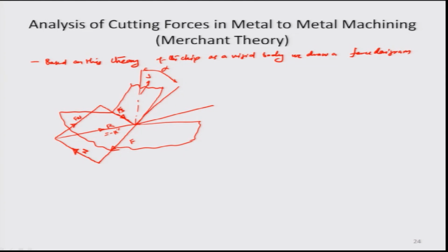And further, there would be a situation where we have a cutting force which the tool gives onto the workpiece. Although this is not on the chip, there is a chipping process happening from the workpiece, and whatever forces are on the workpiece before the chipping has completely happened also influence the chipping process, so these forces are also of utmost consideration. The force that the tool gives to the workpiece would be recorded as the cutting force.